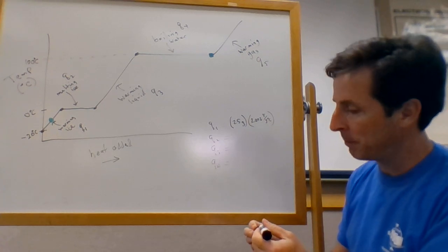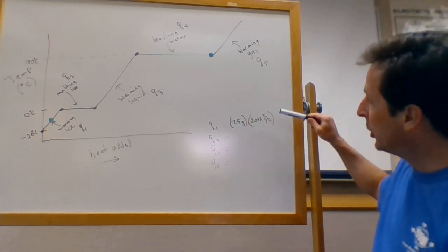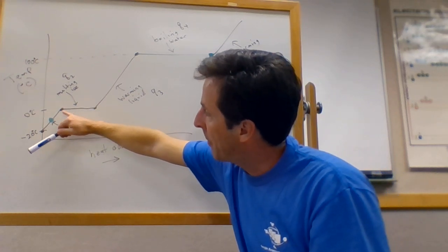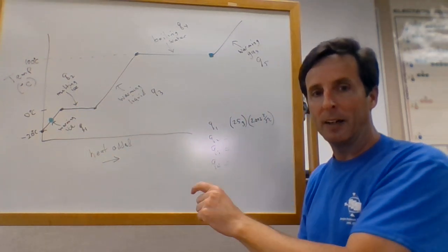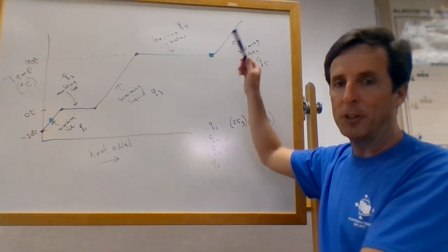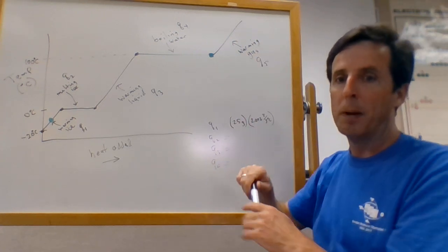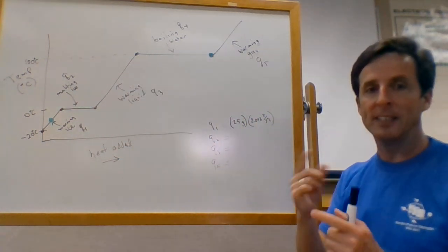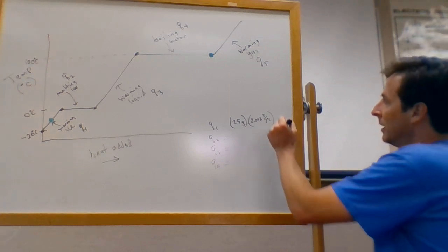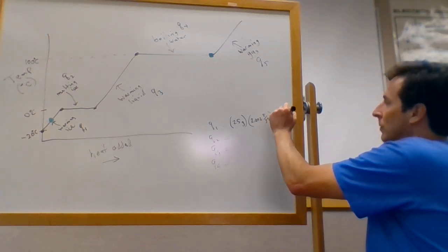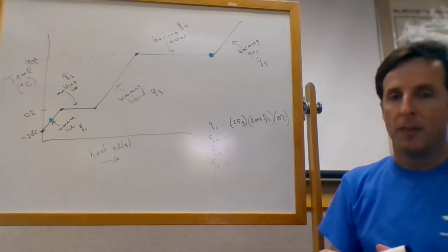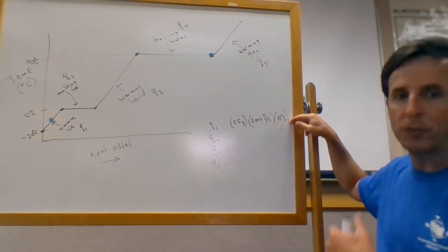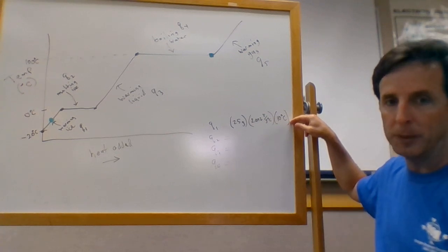Then I have my delta T. In Q1, my delta T, I'm heating it from -10 to 0. Only that part is happening in that leg. Okay, again, students get carried away with the delta T. They want to do all of it at once, but I can only do the part that corresponds to this segment. Okay, so from -10 to 0, that's a change in temperature of 10 degrees. So delta T is going to be a 10. Okay, that takes care of Q1. Calculate that. That'll be the joules required for Q1 to be absorbed.